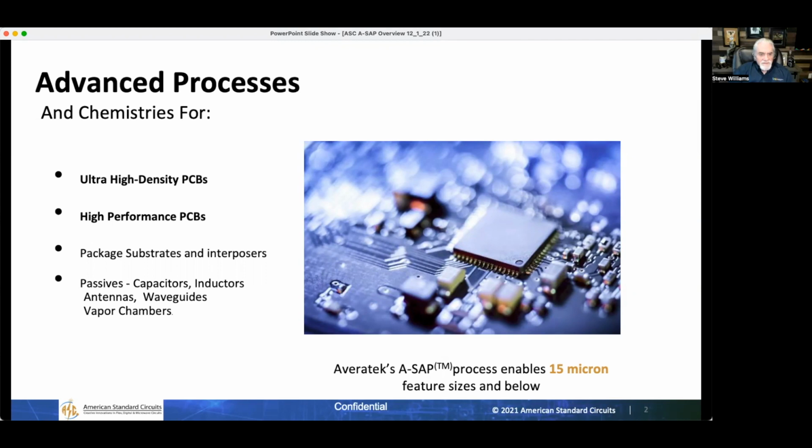Okay. If you look at any high performance HDI circuit boards, they can benefit from this technology, where you have something sub 75 micron trace and space, the old 3 mil and 3 mil lines and spaces. If you have a 2 mil and you have, let's say, via in pad plated over, and you have multiple plating steps, this technology can help in that even, so it's pretty broad ranged.